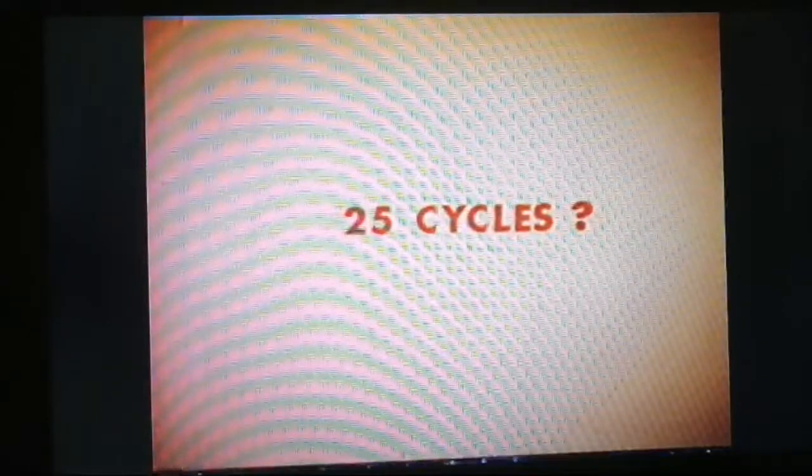You may occasionally come across a 25 cycle generator. These were more common earlier in this century in areas where direct current was used to power streetcars, subways, or large DC motors and equipment. Where large water wheels were used to turn generators, the slower rotational rates produced often made lower frequencies, such as 25 cycles, more practical, and converting lower frequencies to direct current had distinct advantages.